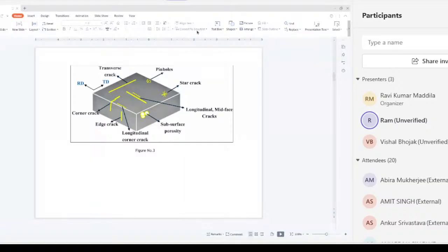And for the developer also, there are different types. Either I can use a dry powder or water-washable developers or hydroscopic developers. So when you get into level 2, you will understand which penetrant or which developer to be used for which material, based on the sensitivity. So these are some images which will give you a feel about what liquid penetrant or dry penetrant is.